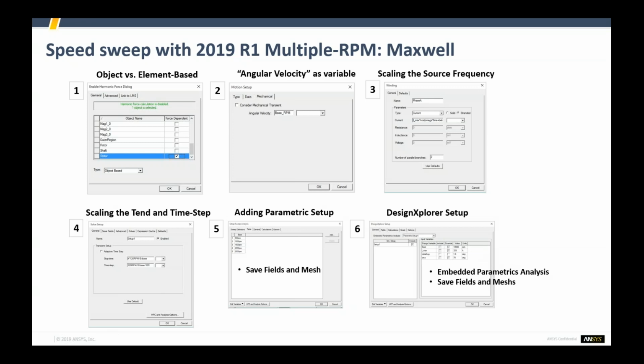It does parametric analysis, and it can save fields and meshes on each time step. After setting these, the harmonic response consumes force densities of different frequencies, and then generates an ERP map in the structural harmonic results.